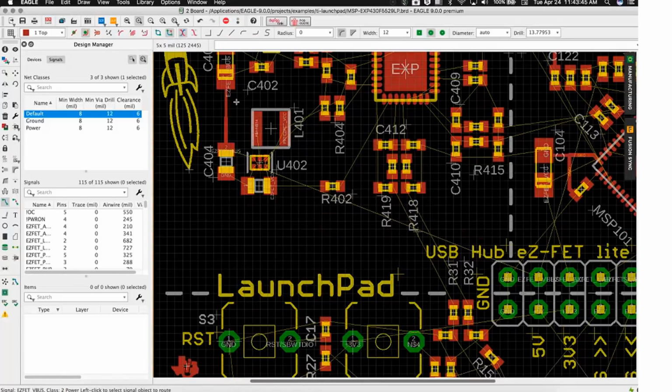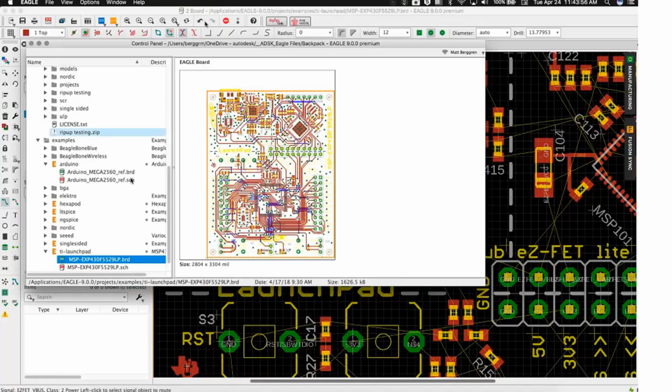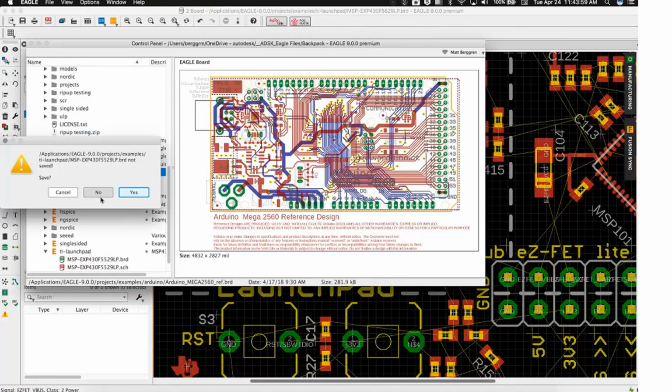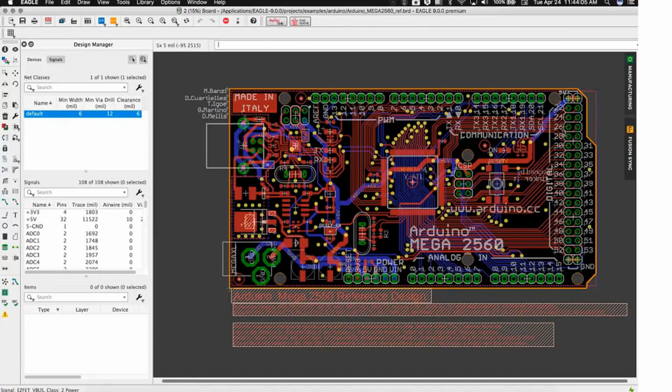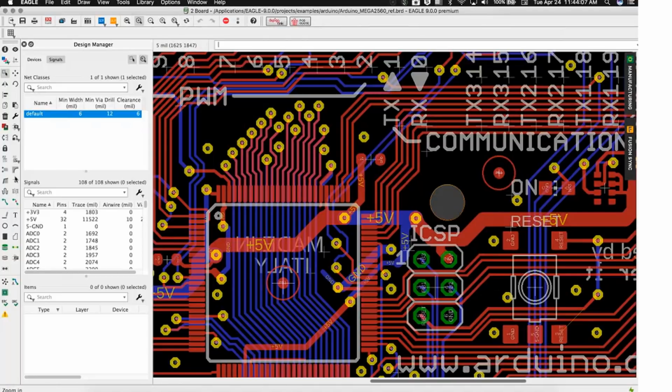So that being said, I think those are probably the primary features other than the cleanup. And I want to show you one last thing, which I think is super powerful, super, super easy, and again, designed to make the process much, much better overall. So for those that don't know, one of the goals in terms of routing a board is always to try to minimize track length, try to remove non-orthogonal connections, try to remove things like acute angles. The smooth signal command here is designed to really evaluate routes and then try to do cleanup on those routes.